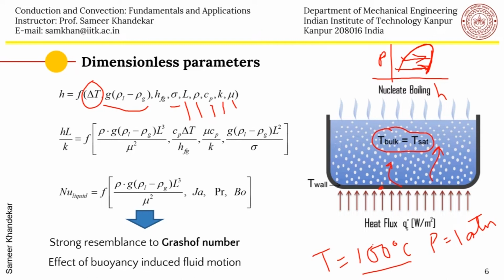So if you apply the Buckingham Pi theorem, you will see that certain non-dimensional numbers come up, which are pretty straightforward. So let's first discuss these four non-dimensional numbers. So this Cp delta T by hfg, this is the sensible heat divided by the latent heat. This is called the Jacob number.